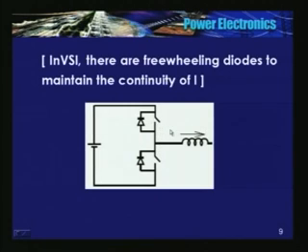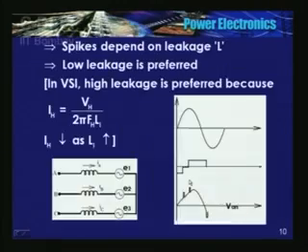The moment I open the switch, I don't need to close this, current will start flowing through this diode. That maintains the continuity in a VSI. So, the L di/dt spike depends on the leakage inductance.